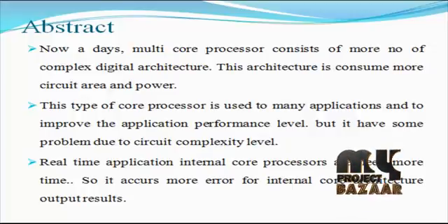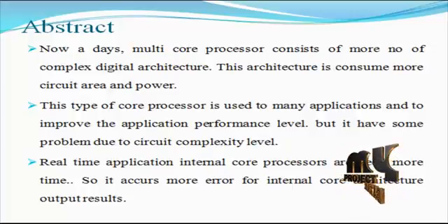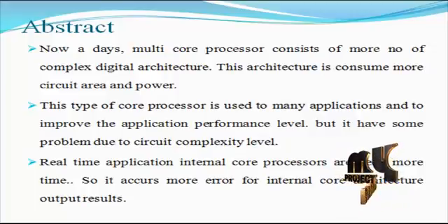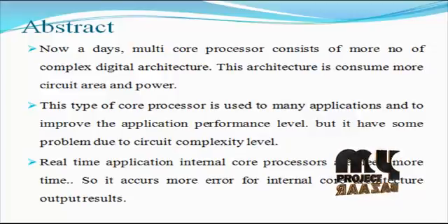The pipeline-based TAM allows for a great deal of flexibility in test applications, and the pipeline helps to improve the test time and reduce the capture power requirement. A partition scheme enables the broadcast TAM to achieve high diagnostic resolution. This scheme requires the addition of a few extra chip output pins, which allow core-level failures to be detected from chip-level automatic test equipment measurements.